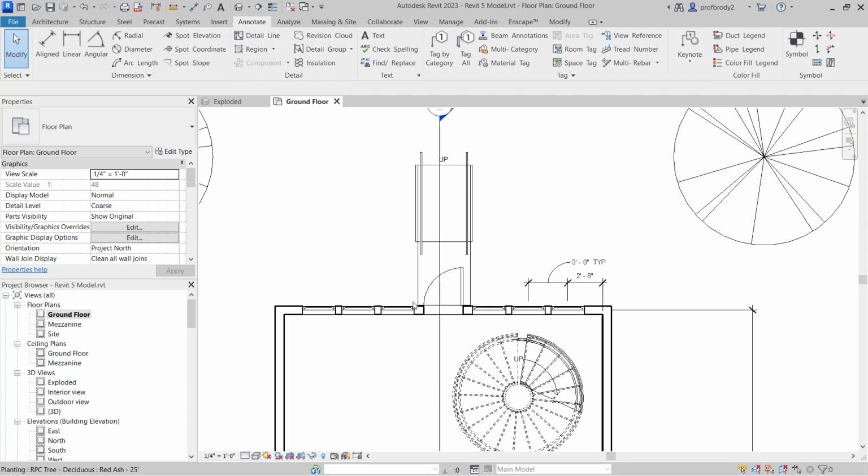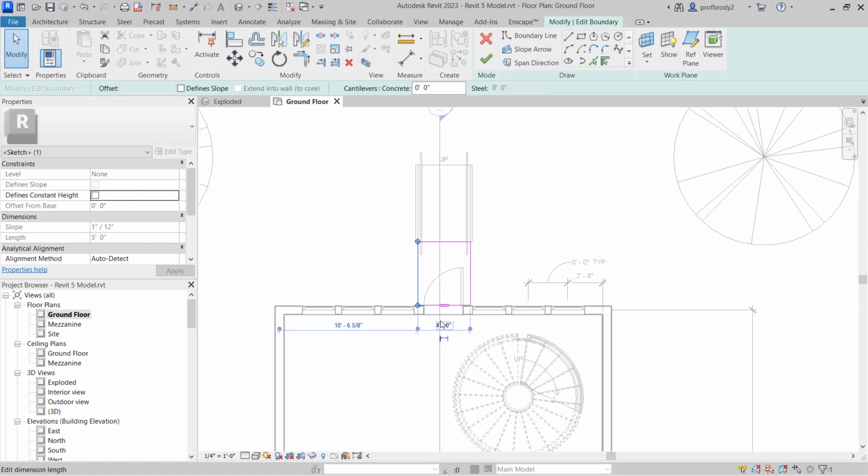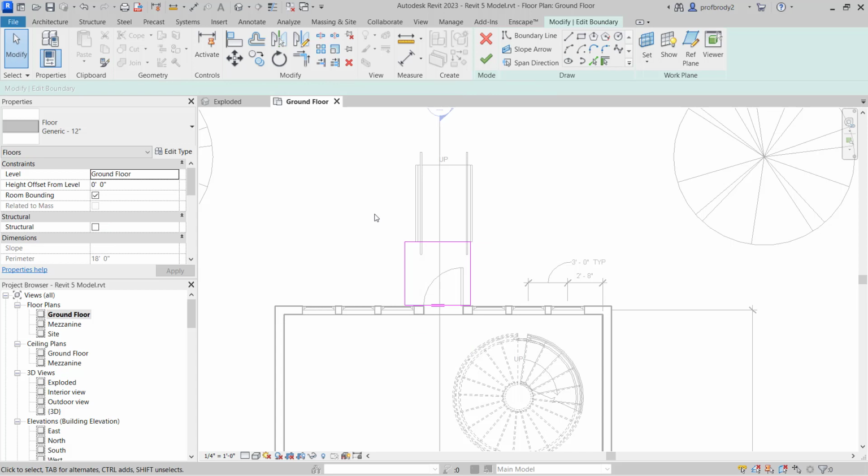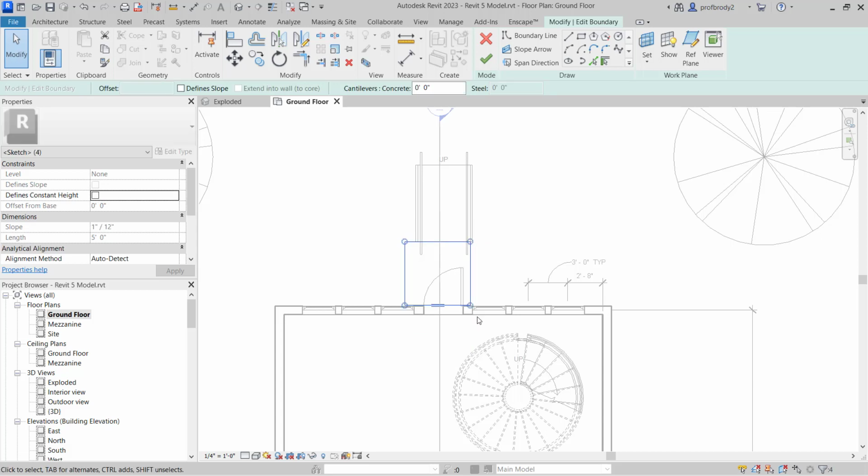You would also want to dimension things like this landing, both the width and the length. And now that I think of it, this landing here is actually not the right size, is it? Because it should be 5 feet wide. You should be able to turn around. So I can just nudge this out, or I can just make this 5 feet. And there we go. Ooh, except I moved it to one side here. Let's nudge that little guy over there. I just love the nudge tool.